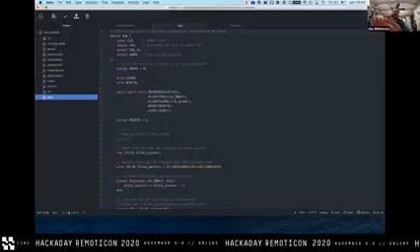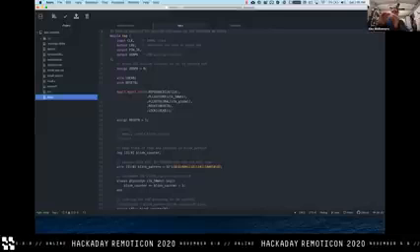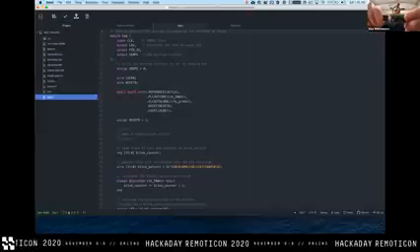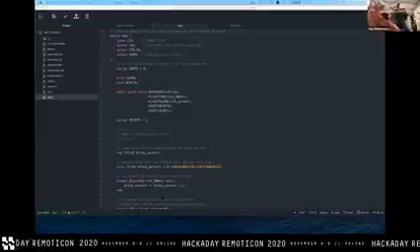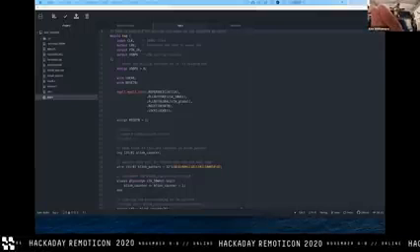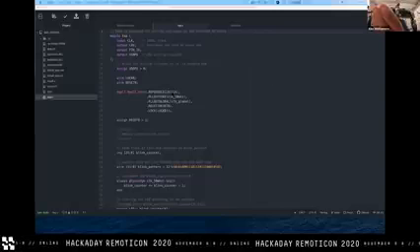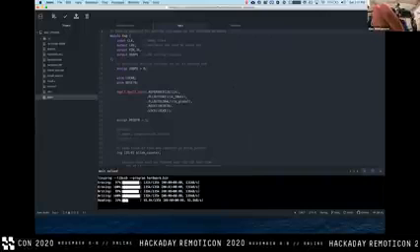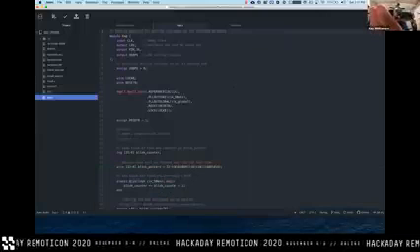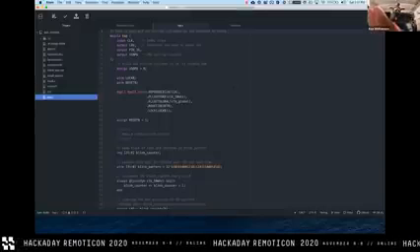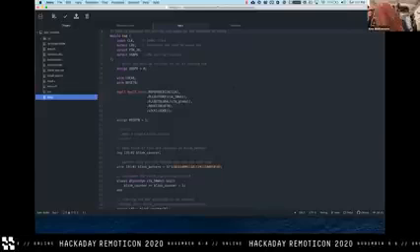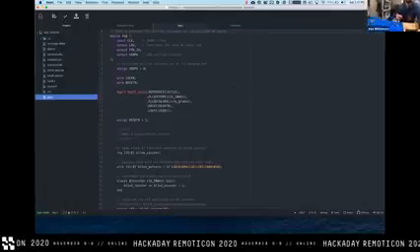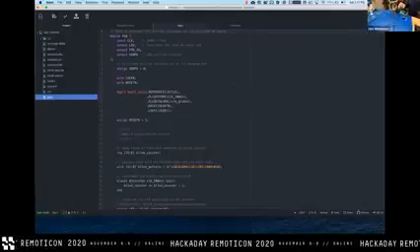I'm actually going to show one thing quickly before I get any farther. Notice how there are 2 LEDs and one of them is lit brightly and the other one is not. Let me reset this. We see that that bottom LED is now pulsating, right? And it's pulsating between 0 brightness and the brightness of the LED adjacent to it. When I program this again, basically it's in bootloader mode. Now it's actually running the gateware. Notice how it's a little bit dimmer. It's dimmer because I'm just blasting a 50 megahertz signal out onto that LED, which, yeah, don't do that or you won't pass emissions.